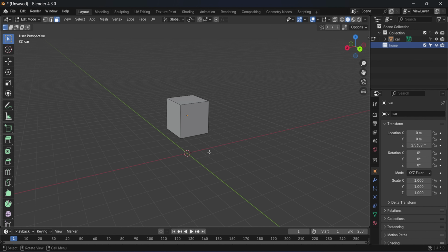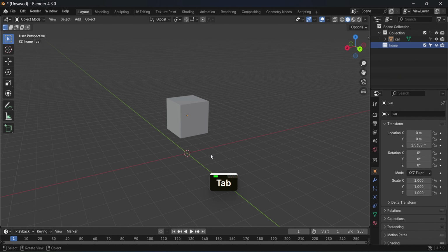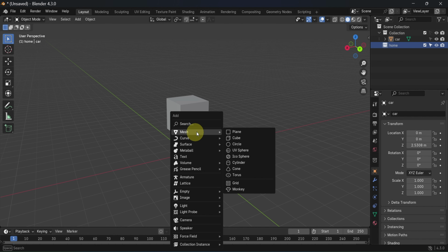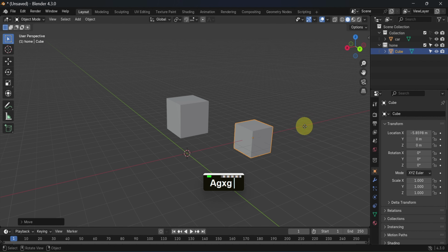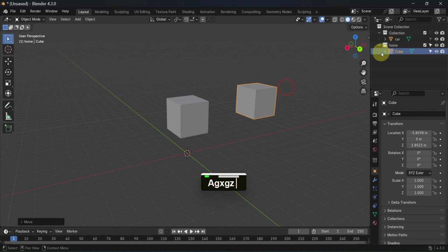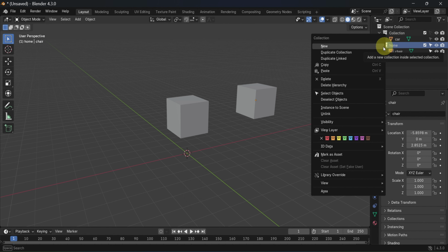You can switch to the structure of the basic object with the CTRL and Z keys. Let's press Shift and A to select a new object and then add a cube. This cube is allocated to the most recently opened collection. Each collection can now be edited individually. The name of the new cube we added can also be given. The menu of the collection is here. We will look at this menu in detail in the following lessons.